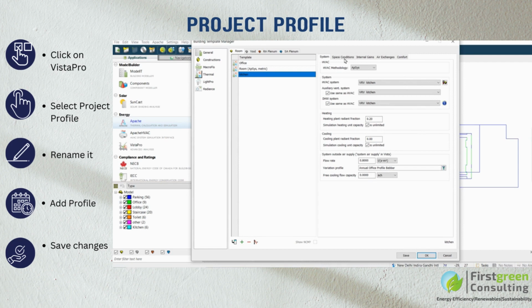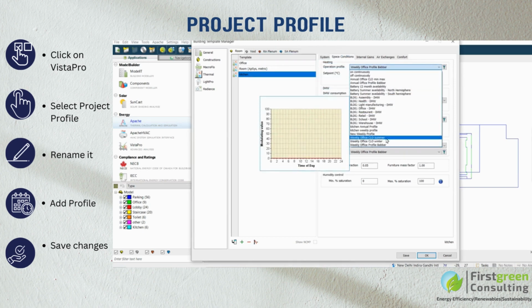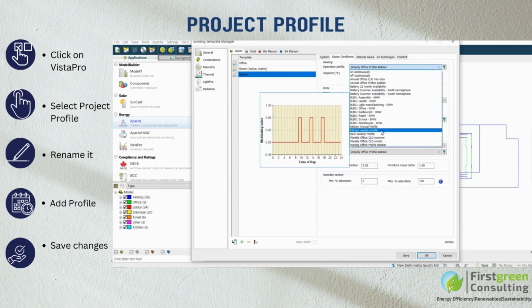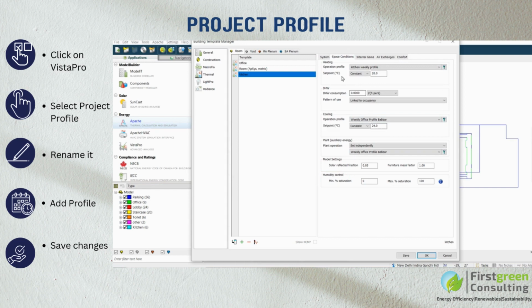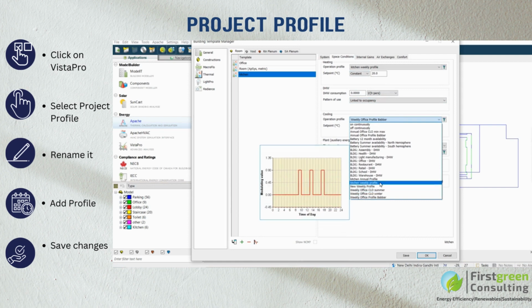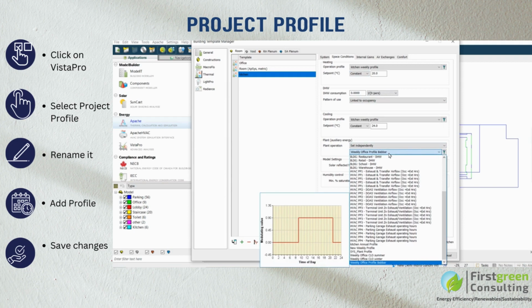Navigate within the dialog box to find and select the kitchen category. Within this section, direct your attention to space conditioning. This is where the transformation unfolds. In this zone, the transformative process takes root and begins to flourish. Replace the current designation of office profile with the newly designated and tailored kitchen weekly profile. For more guidance on this step, refer to the video demonstration that accompanies these instructions.